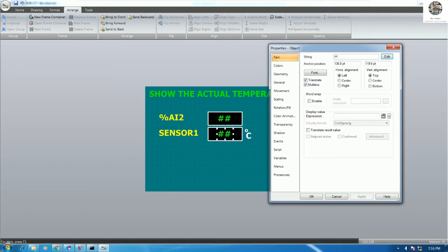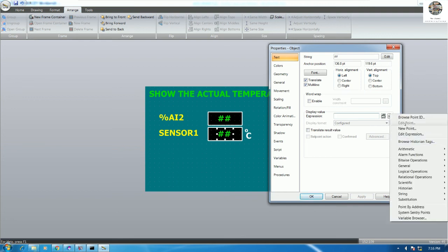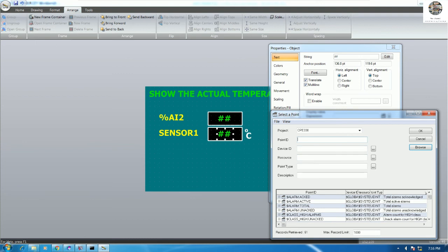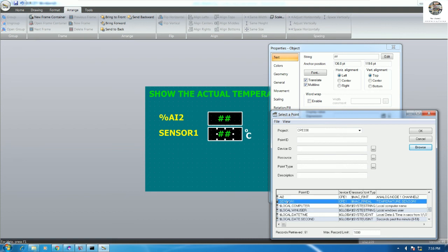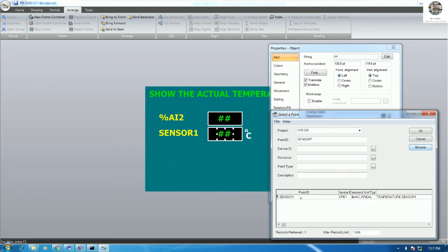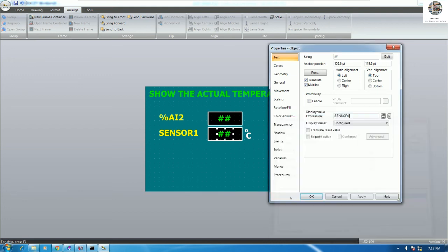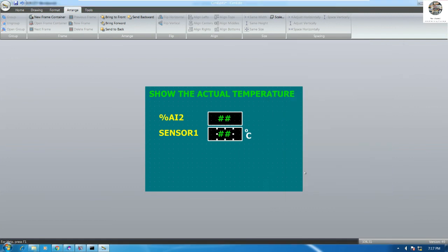And for this one I need to put the actual value, right? So browse, and then go to see the sensor 1 here, or we can search like this. Example, type sensor and then star and click browse. We will filter only sensor 1, and it is the real, right, and it is the precision. Example 2. It means that the decimal is 2 places.